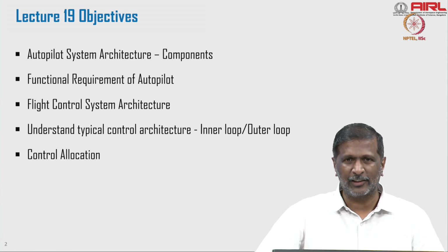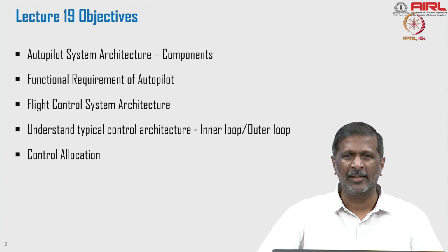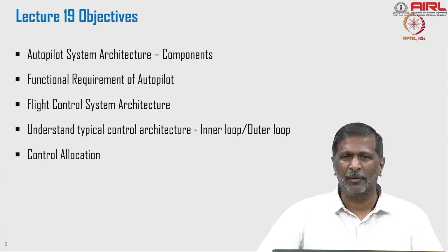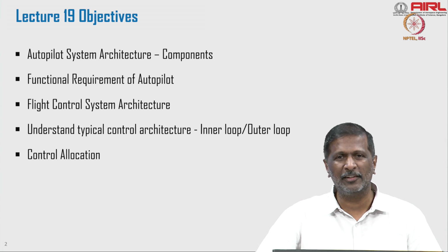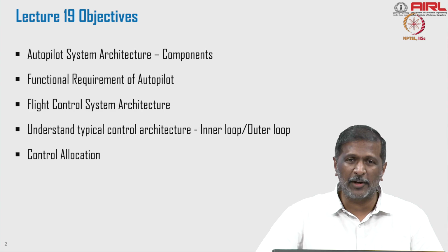Once the control produces an output, what will the control say? I want U1, U2, U3, U4. U1 is going to be my thrust. U2, U3, U4 is going to be how much pitch and roll and yaw I'm going to have. But I cannot directly give the thrust to my rotor. For a quadcopter, you have 4 motors. For hexacopter, you will have a different number of motors. Octocopters, we have a different number of motors. You may have a tricopter, right? So how are you going to convert the input to a control?